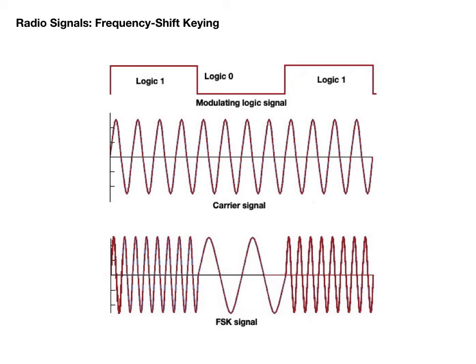When the transmitter is perfectly adjusted so that no carrier or opposite sideband is present in the transmitted signal, the effect is the same as when shifting the carrier frequency. This method is called audio frequency shift keying, or AFSK. While it's possible to use just about any frequency shift, the amateur radio standard is 170 Hz. That is to say, there is a 170 Hz difference between the mark and space frequencies.